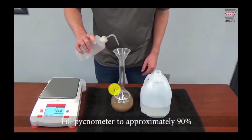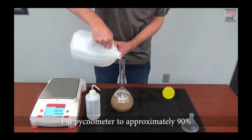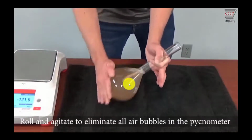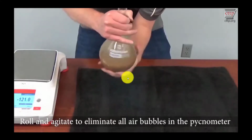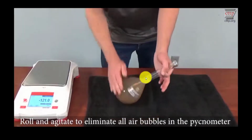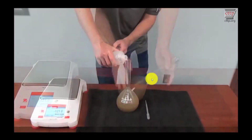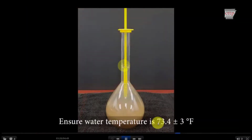Over here, the SSD weight of a fine aggregate has been added into half liter water, and then you remove any sort of bubbles present in it, so that it can give the accurate result up to this marked value. After doing so, you will add a little more water so that it will reach up to the level mark. You must ensure that it is at 27 degrees Celsius, 73 Fahrenheit.